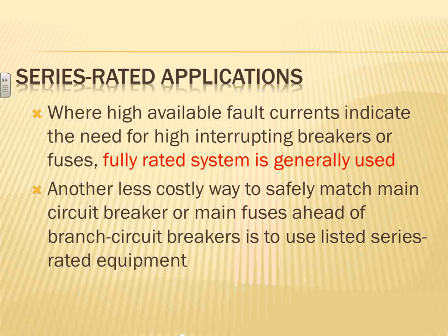And there's nothing wrong with using the circuit breakers as a feeder protector, and then downstream you go and fuse to protect the equipment themselves. There's nothing wrong with that. Supplemental protection.